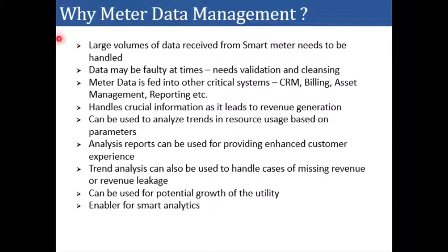Now let us try to understand why the meter data management system is required. As we know, the large volume of data received from smart meters needs to be processed. So for that, the meter data management system application is required. The data may be faulty at times. That means we need validation and cleansing.